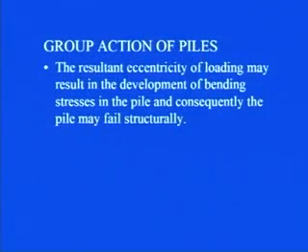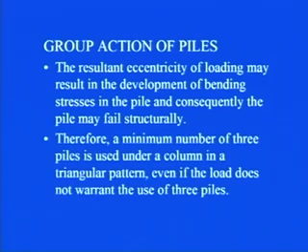So, the resultant eccentricity of loading may result in the development of bending stresses in the pile, and consequently the pile may fail structurally. As I told you, any eccentricity between the loading and the CG of the pile will cause bending stresses in the pile and subsequently the structural failure of the pile. Therefore, a minimum number of 3 piles is used under a column in a triangular fashion, even if the load does not warrant the use of 3 piles.